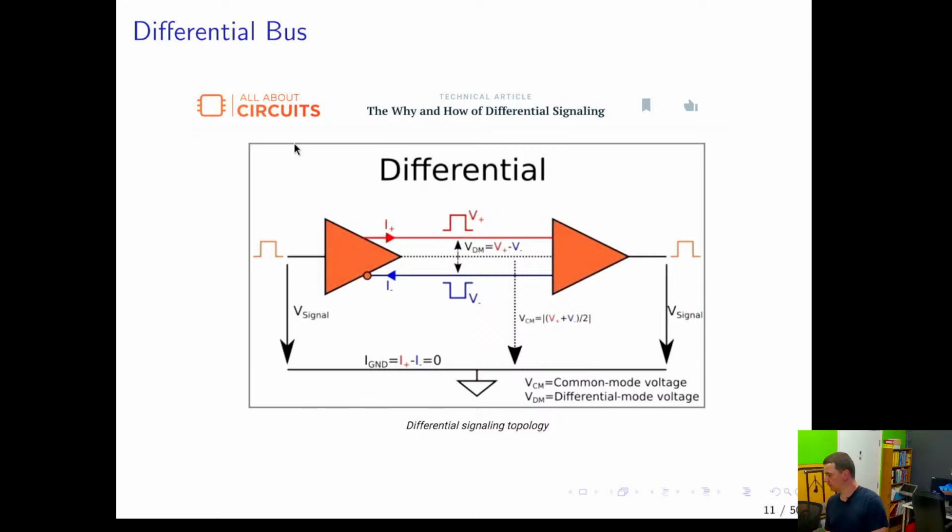Does that, since you have a pair going across, negate the need to synchronize the clocks, because it's going to be expecting one and one at the same time? No, you still need the clock because these things are identical. Even if you knew they're coming identical, you still wouldn't know how long a bit is. You need the clock because you wouldn't be able to tell 2 bits from a single bit.